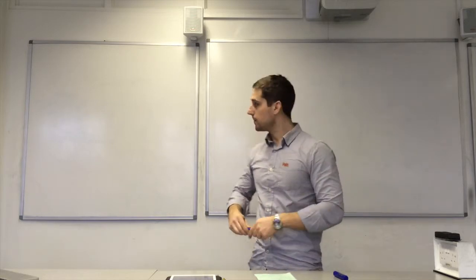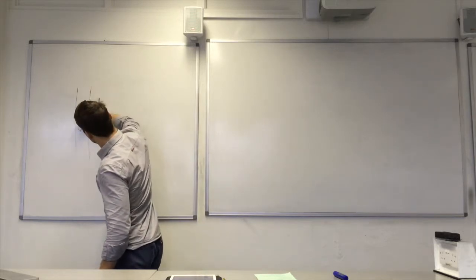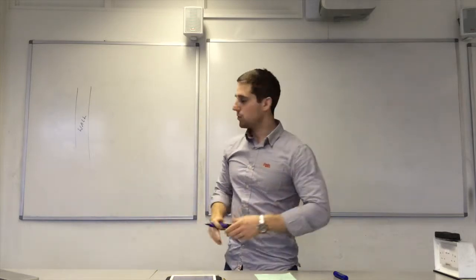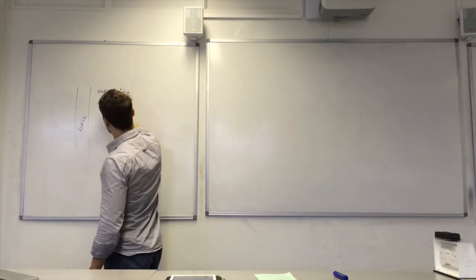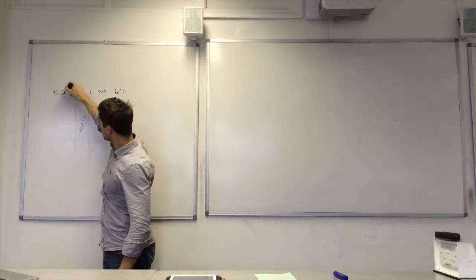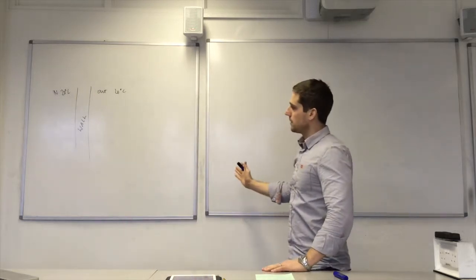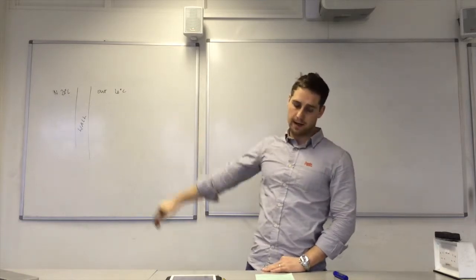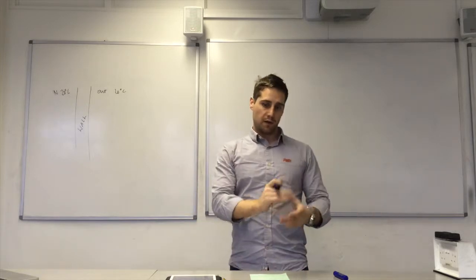conduction and radiation. So we'll take our wall here. That's my brick wall. And in this particular situation, the outside is about 26 degrees C and in is about 20 degrees C. So it's warmer outside than inside in this case. So the heat transfer will be from the outside in, because it's always from a warmer region to a cooler region, the heat transfer direction.